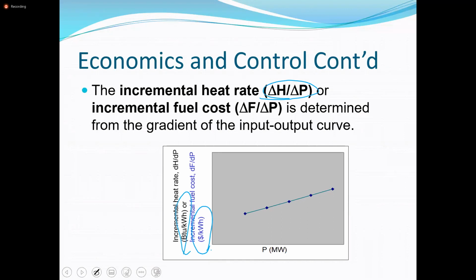Now, what I want you to note carefully is the fact that when we find that differential, the incremental fuel cost will be increasing as the output increases, which is what I said earlier, that even though I have one line from my production which is cheapest, as I increase the output of that line, the cost to produce an additional unit will cause the overall cost to increase.